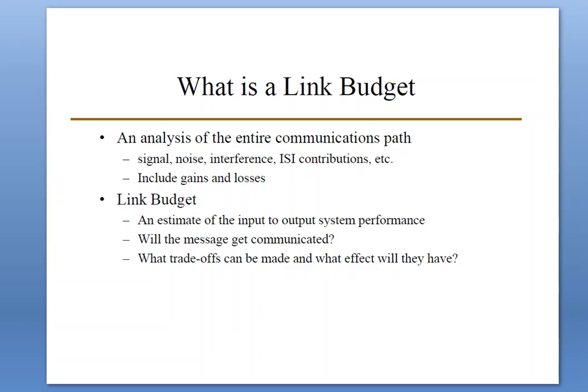For example, from the link margin, one learns whether the system will meet requirements comfortably, marginally, or not at all. That means it is an examining test of whether the particular system parameters meet the grading mark or not. The link budget may reveal if there are any hardware constraints and whether such constraints can be compensated for in other parts of the link.